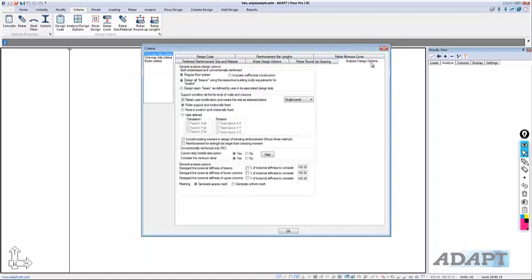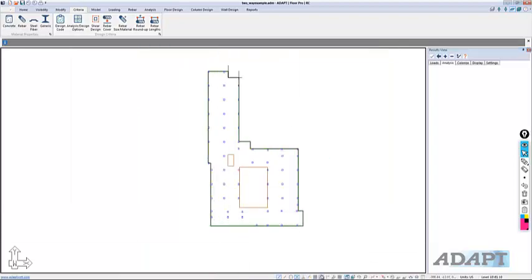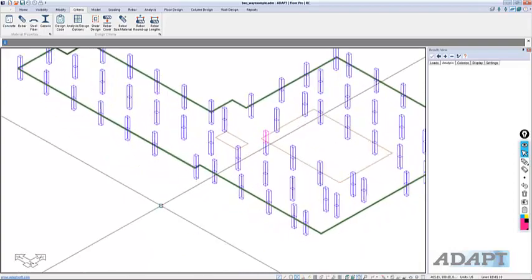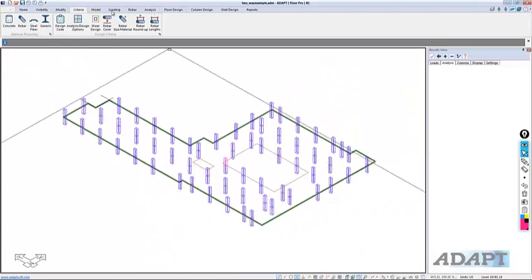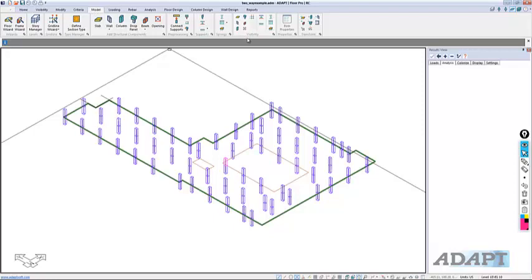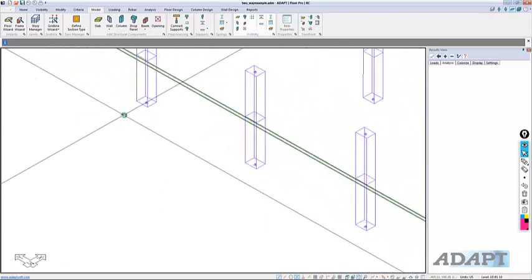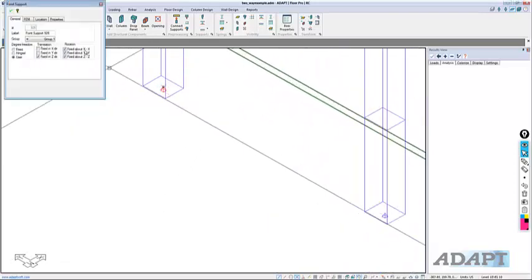But under the analysis and design options, when the user analyzes the single level model, the program assumes some support conditions, and it's assuming roller support and rotationally fixed. Earlier I mentioned that when we analyze, the program auto-assigns supports. These are the supports it's auto-assigning, and before or after you analyze, you can go under the model tab and, using this visibility panel, view supports. So you can see supports at the base. If I double click, it's a fixed roller.